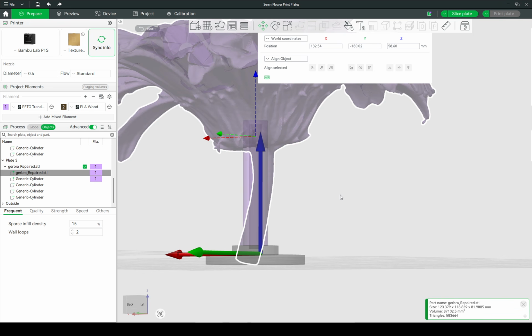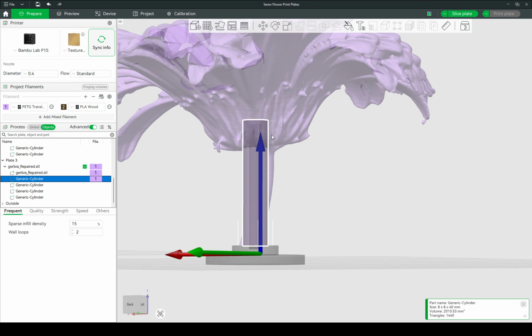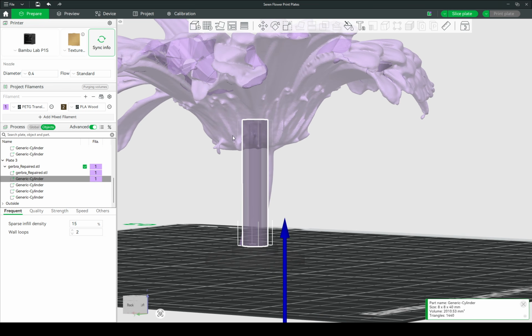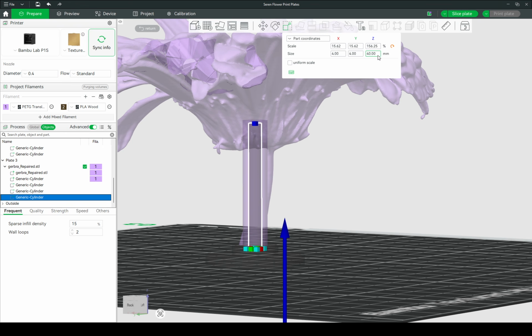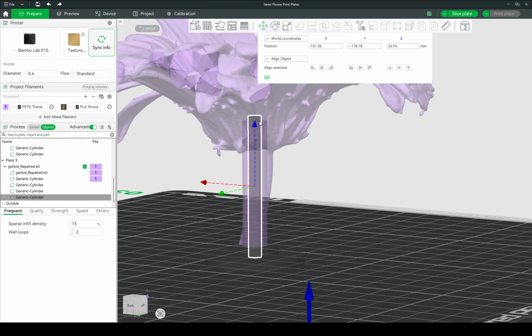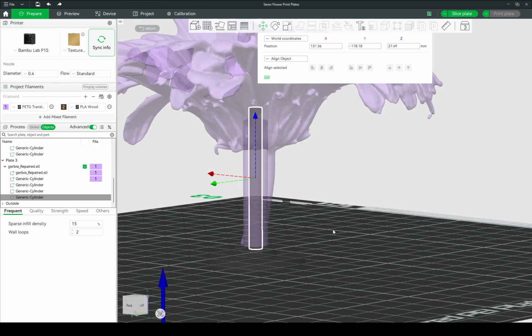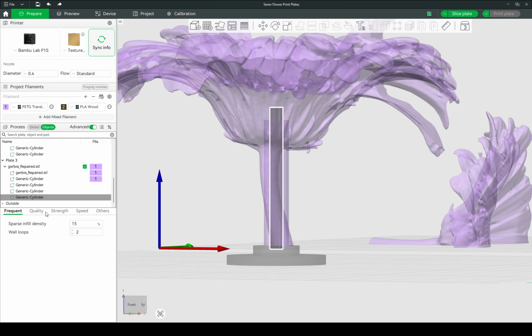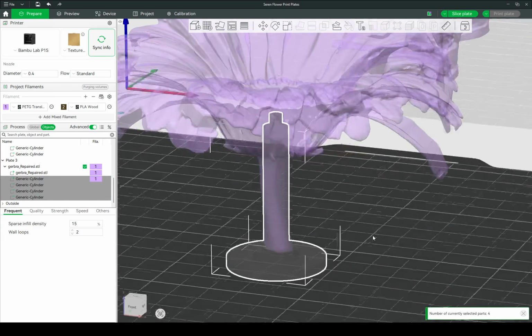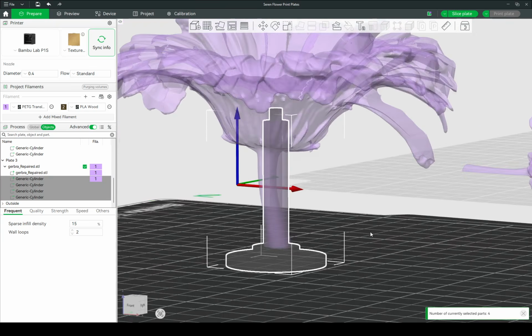I want this part here, I want this little cylinder here just to kind of poke through a little bit. So I might even change the length of the negative cylinder. So I'll go here, change its length to 45. That'll change the length from the middle out, so you need to reposition it a little bit, but just like everything, we're just eyeballing it. Okay, so that is pretty much it for our little sub-assembly here of mostly negative parts.